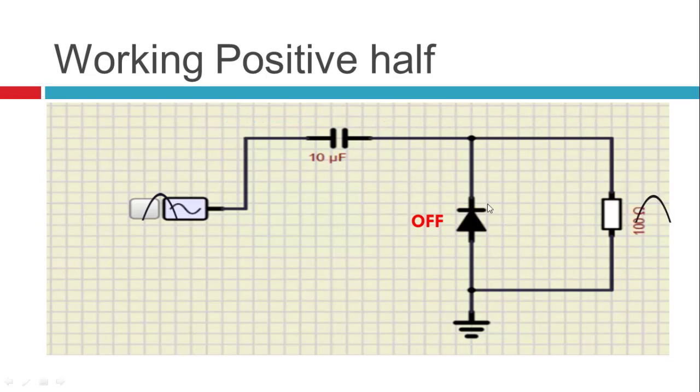And because AC is already appearing, this AC plus the voltage due to the stored charges gives some positive voltage across the output, and because of this the AC is raised by some level. So this charging and discharging of the capacitor raises the voltage level of the AC to the positive side.